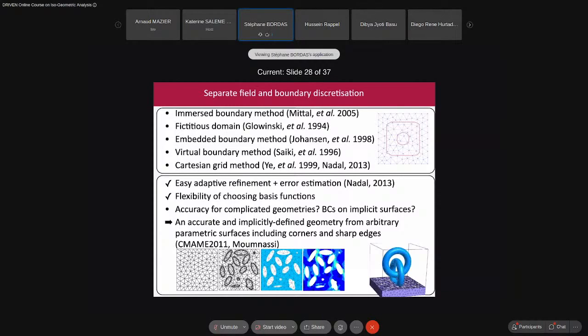So sometimes you have a more dilute mixture, and sometimes a slightly denser mixture, in which case generating the mesh is even harder, because the rods can get arbitrarily close to each other, which means that the elements between two rods which are quite close could become very small. On top of that, the mesh has to be constrained to stick to the boundary of the rods, which is an extra constraint. And if the elements are small, that can lead to the mesh generator failing.